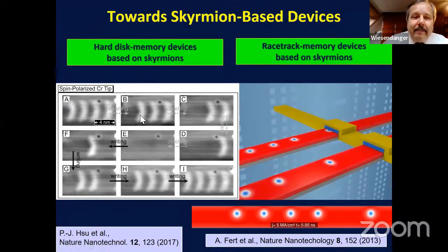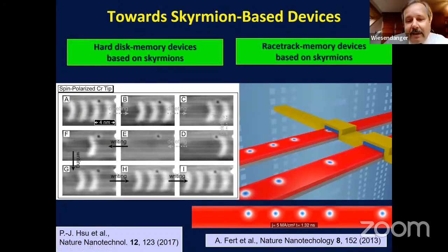Of course, there was another famous proposal by Albert Fert and co-workers in Paris immediately after our discovery that indeed individual skyrmions can exist. The Fert group published this paper, basically proposing this skyrmion-based racetrack memory, and also showing that this could have great advantages over domain wall-based racetracks as proposed earlier by Stuart Parkin. Now, the problem was, of course, and we have noticed that, that you have then to detect the passing of skyrmions, say, by some kind of tunnel junction.